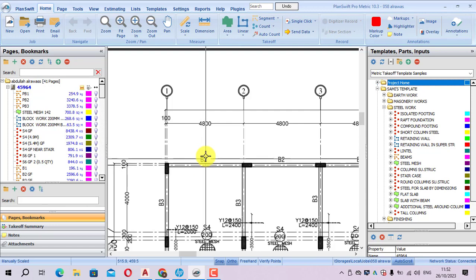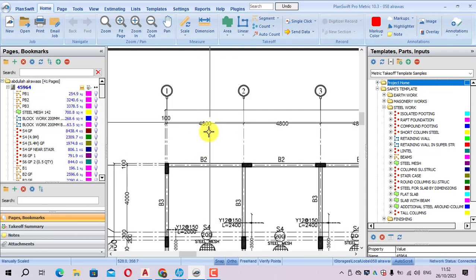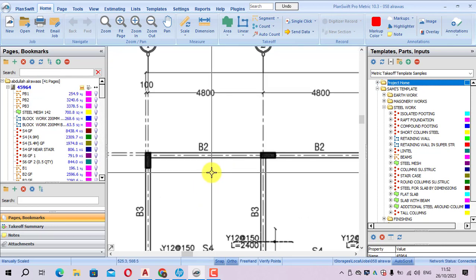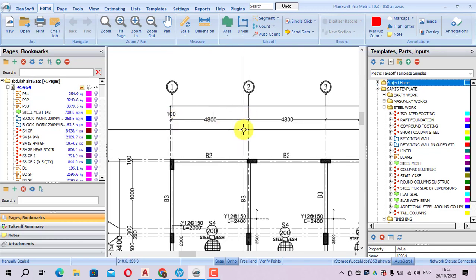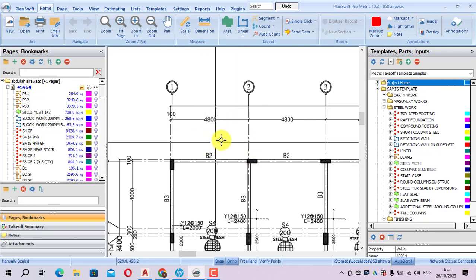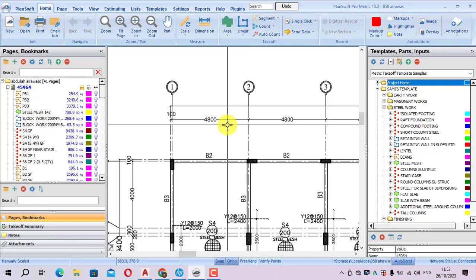Anyway, in steel I will not take it like this, because I need the measurement of concrete and shuttering the same. So I will forget the steel overlapping; I will add 10% for steel. When I finish all the calculation, then I will multiply the quantities by 1.1.